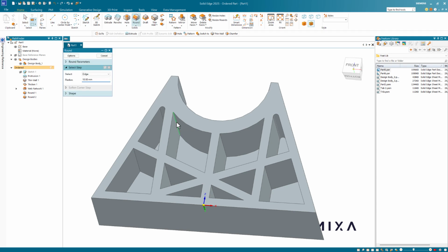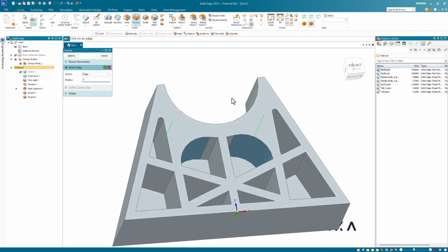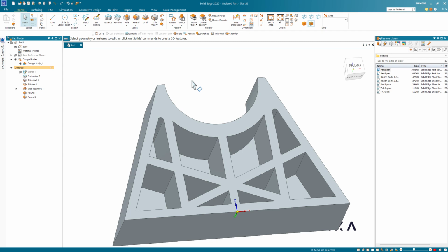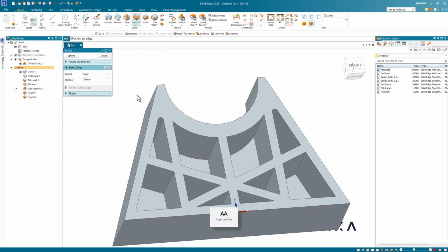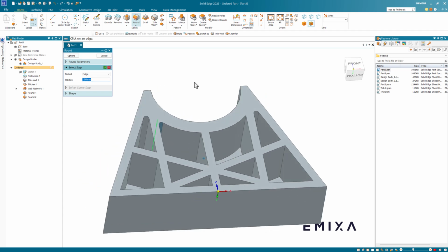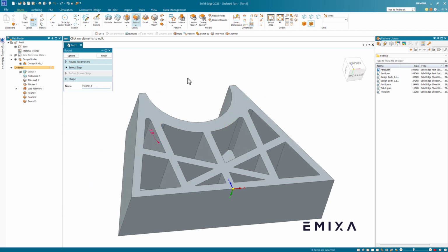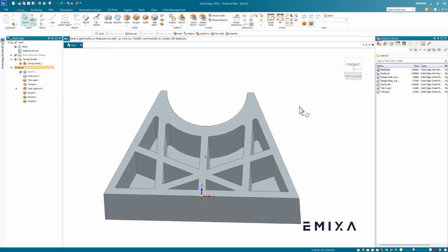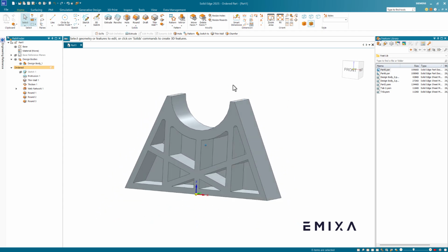Okay, let's go and pop these two back in because I changed those before I'd finished. If you're doing these values, notice that it keeps setting to 5 and 1. A good thing to do, what I find, is go into the radius and then escape once you've changed the value. If you then go back in, so if I press tab and then cancel on there, that will normally remember your previous setting. So now I've done that in 1. Next time I go, that's going to remember it. So sometimes go in there, create the feature, delete it if you want to get that back to a standard size. Okay, so we've designed that.